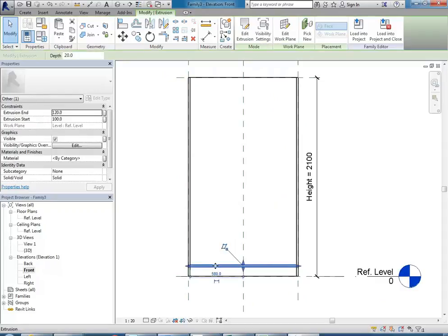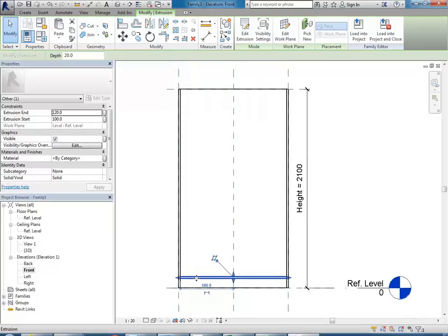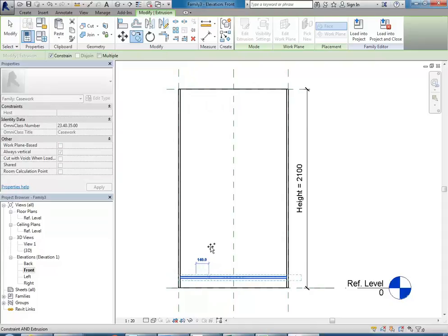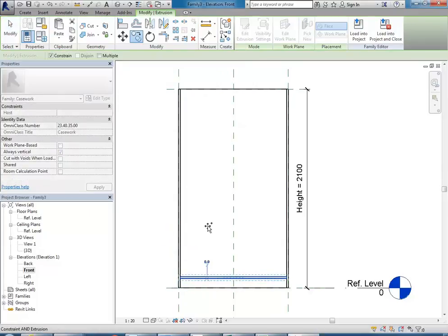And then going to the front elevation, I'll just show you one last thing. Actually, you don't want to go too far with this, but with the extrusions you make, if you try to copy them, you might see this happen. So you may have already come across this when you try to copy up and down. So notice if I select this one and then copy, click to give a base point, and I can't go up or down. You seen that one? It's a common thing with solids.